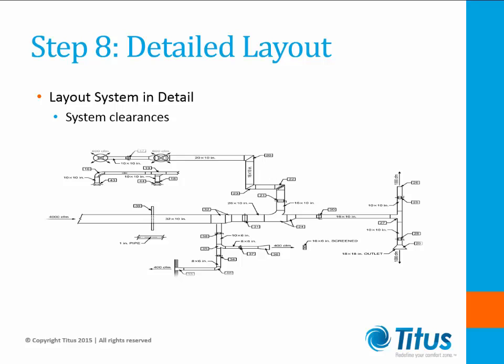If rectangular ductwork is being utilized, it can be transitioned to larger aspect ratios to fit over impediments or high ceiling areas. As a rule of thumb, though, I never exceed an aspect ratio of 4:1. Another method for transferring over limited height areas is to utilize multiple duct runs. Examples are given on Table 7 of the ASHRAE Fundamentals 2013, Chapter 21.